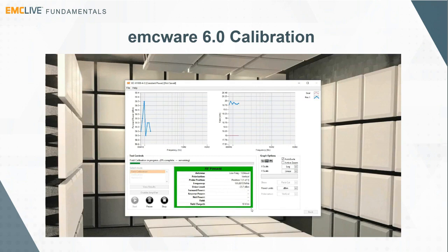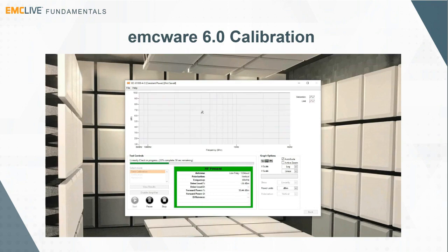So you see the system will now run. You can read your information that's on the signal generator and power output. It's always good to monitor, and it's also being graphed here. The level again is 18 volts because we want to test it at the higher AM modulation point. Then we're going to test linearity to make sure that at that 18 volt CW calibration point, we weren't in saturation. Dropping power back by 5 dB and noting that the change is still at 5.1 dB and it was not in saturation.